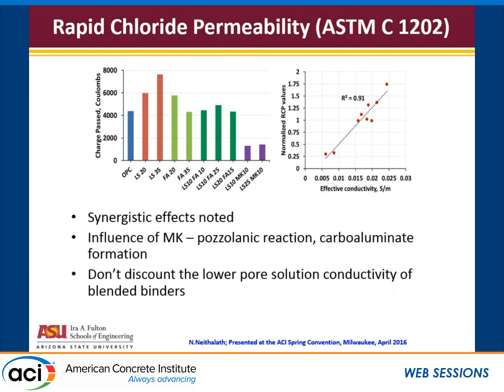So if you look at RCPT, again, this is not a very good experiment, but still for specification purpose, if people are still looking at it, you can see that limestone alone at 28 days, really 20 and 35%, so not the 5% that we normally do, very high amounts, really doesn't do much. Your chloride permeability is much higher, which is not good.